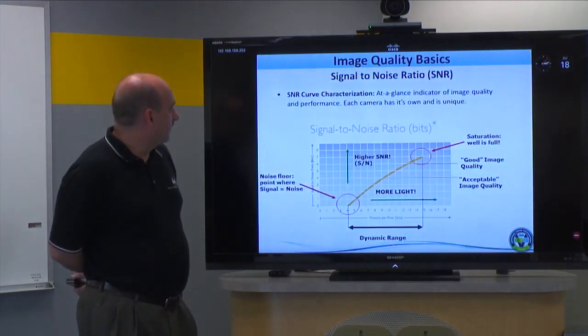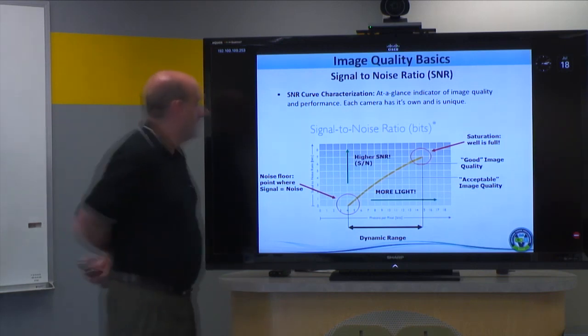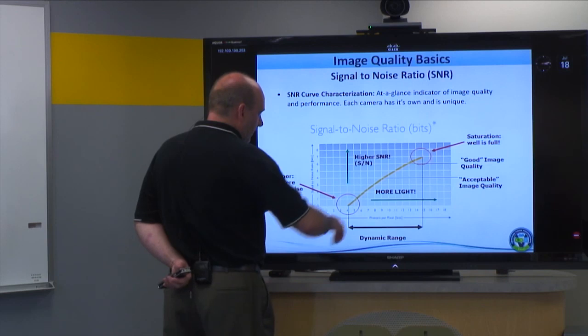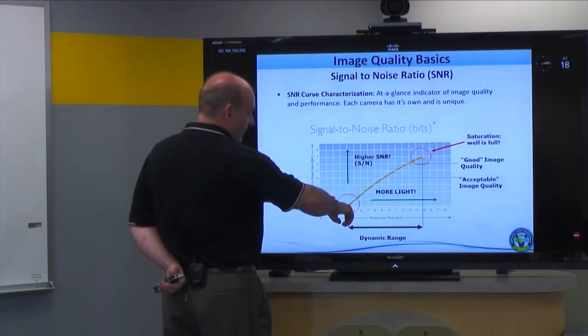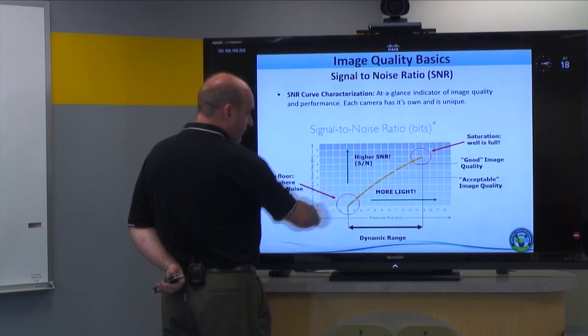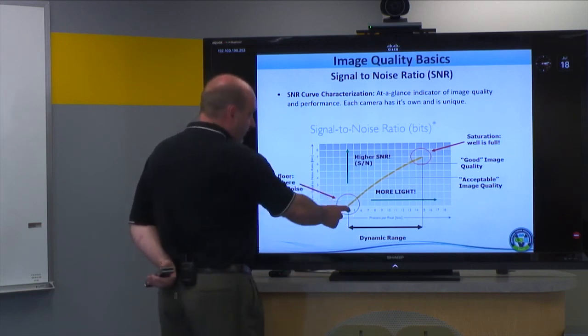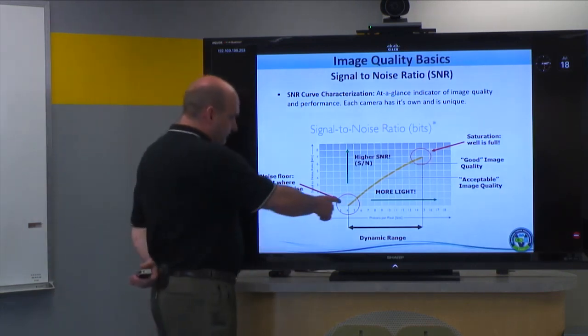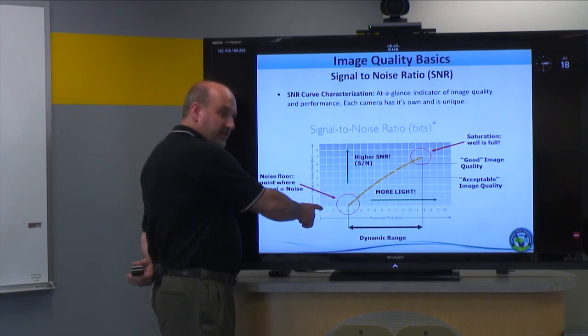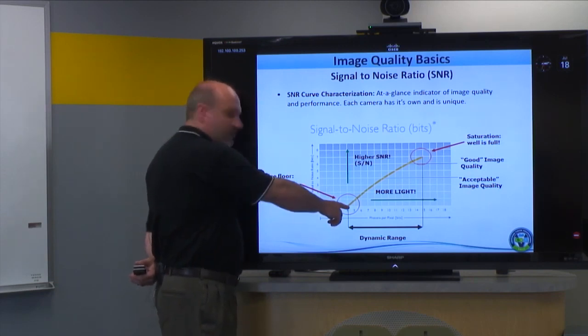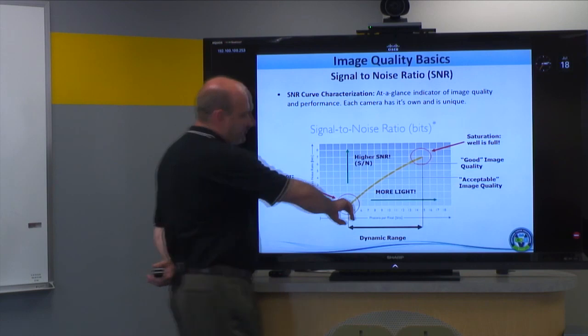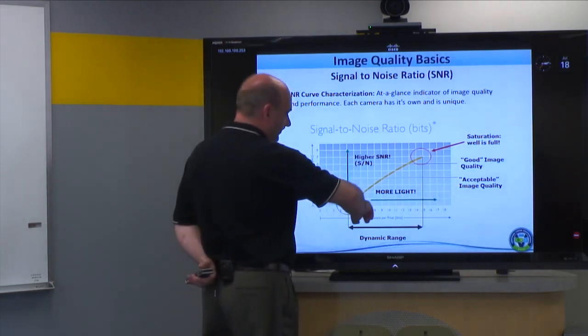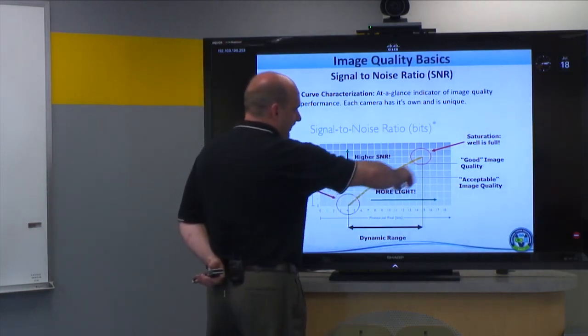So this again is showing the signal-to-noise ratio and how this affects the camera's output. This is the point at which the camera has no photons in the well, or the black level of the camera, so the output is driven to 0. That doesn't mean cameras are necessarily single photon devices. It doesn't mean there might not be light hitting here, but it means this is the minimum light that this camera can detect. And this camera is set in more or less a linear mode, so as the light doubles, the output doubles.